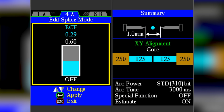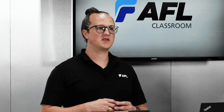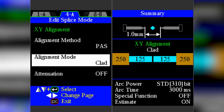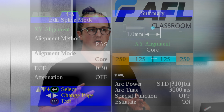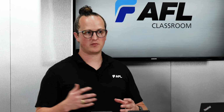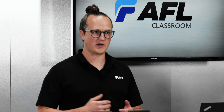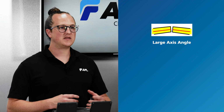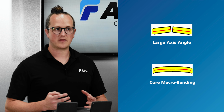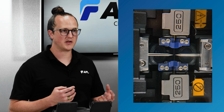the splice. When fibers with poor core cladding concentricity are spliced with cladding alignment, you're very likely to see a core offset. This can be corrected by changing the XY alignment method to use core alignment instead of cladding alignment. Note that this only applies to fibers where the core is visible. Polarization maintaining fibers and others like it are not compatible with XY core alignment. When fibers are spliced with a large fiber axis angle, you'll tend to see core macro bending. To correct this, ensure either the cladding only or the coating only rests in the V-grooves. Also ensure the grooves and the fiber are properly cleaned.